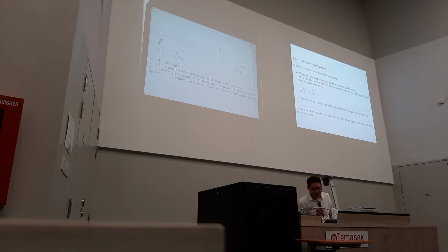It's a very long definition, but it's basically telling us that based on this damping coefficient, after we put in some disturbance, we can see how well the system buffers or damps the changes. Every time we change the input or the disturbance, the system will fluctuate. So the bigger the damping coefficient means that it fluctuates less.